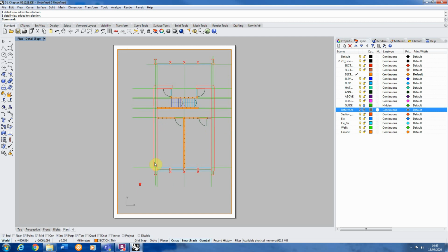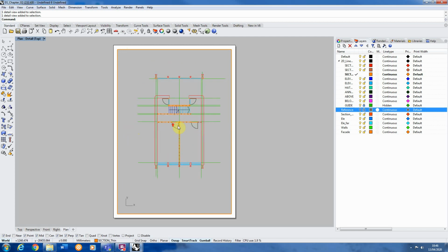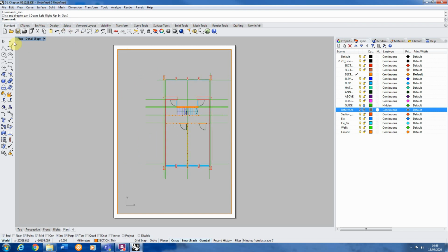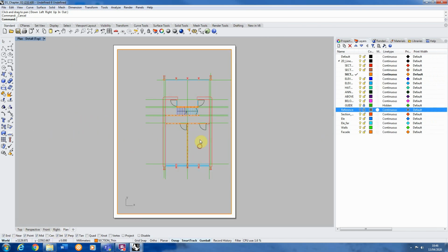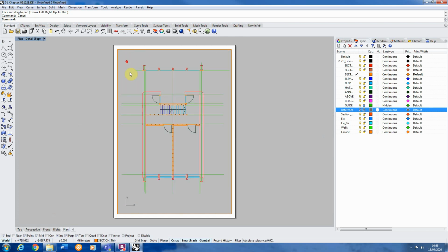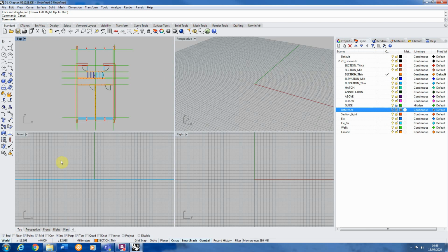It's a window in to that model view, and therefore we can scroll it till it's around the right scale. We could pan it if it's a big drawing to focus in on different parts. And that is essentially just looking back into this view here. I would never work on any drawing or any modelling in your layouts. You just want to use it to frame your views. Any modelling work you should be doing in your views here, in your model views.